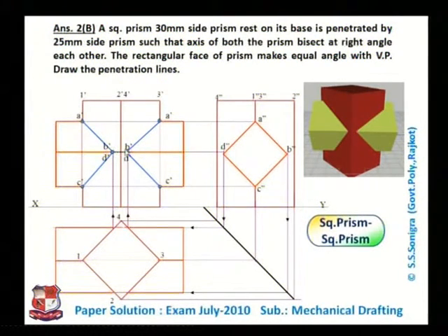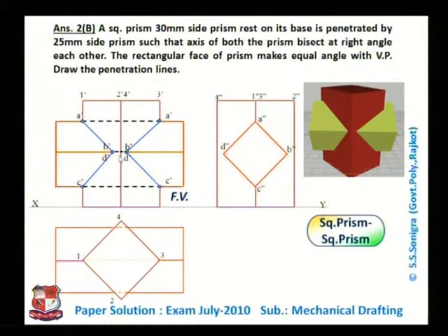So here in this portion, dotted line would be there. So let me draw that. And here also this edge, upper edge, which is inside this prism, will not be visible, hence drawn by dotted line like this. So this is dotted line, this is dotted line, and this intermediate is also dotted line. So it should be drawn like this. This dotted line, this and this, and rest all lines should be either made much lighter or they should be erased. So this edge, upper edge of this horizontal prism is shown by this dotted line over here like this.